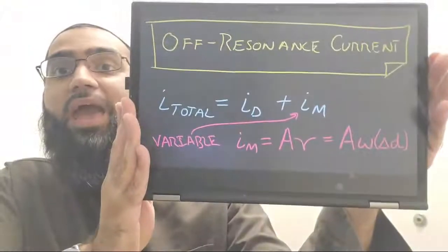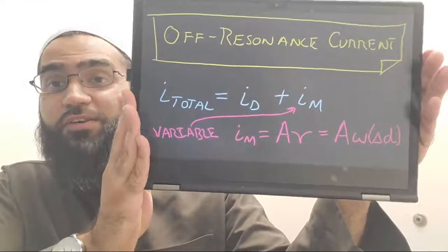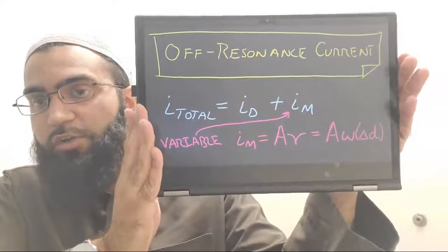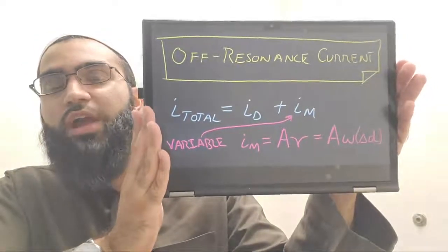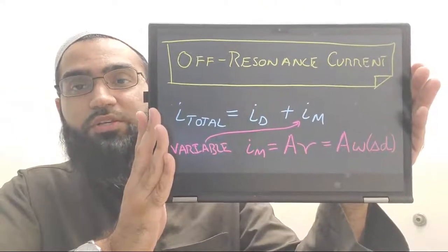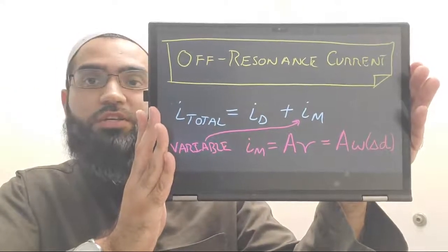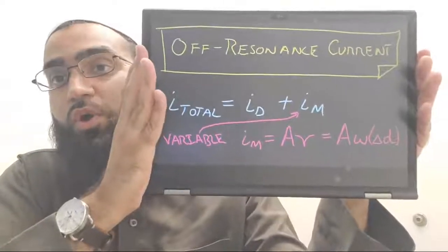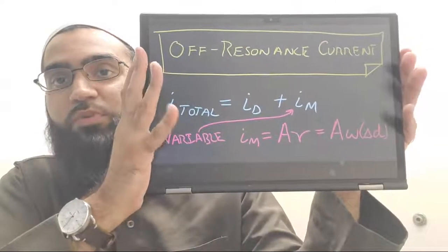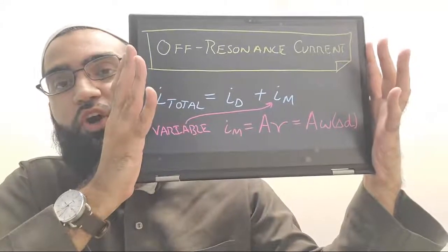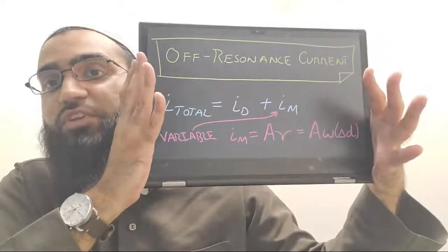And the next part here is the mechanical current. This is the interesting stuff. This is how you can use the current of your piezoelectric device, the off-resonance actuator, as a sensor. So piezos have self-sensing capabilities. It's really quite frequently utilized, the self-sensing capability of a piezo actuator, that the current can be used to tell, or even the polarization can be used to tell, the displacement or the velocity. So in this case, it's not a capacitance you're dealing with. You're basically dealing with the current generation source, which has to do with a velocity term.